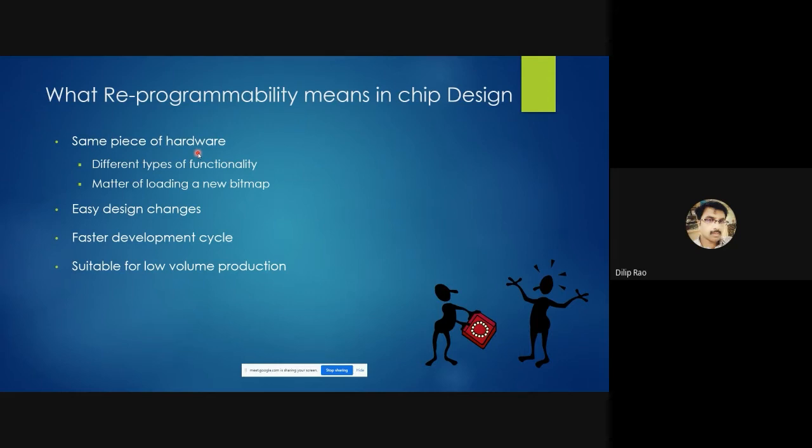So what you do, the most popular and easiest way for you to get this done, is to implement your idea or your design enhancements, whatever you have in mind, in code. You build a netlist, build a bitstream, and download it into an FPGA. The FPGA is just a vehicle here for proving your concept, to prove that the concept you have in mind is capable of performing to the extent that you are claiming.